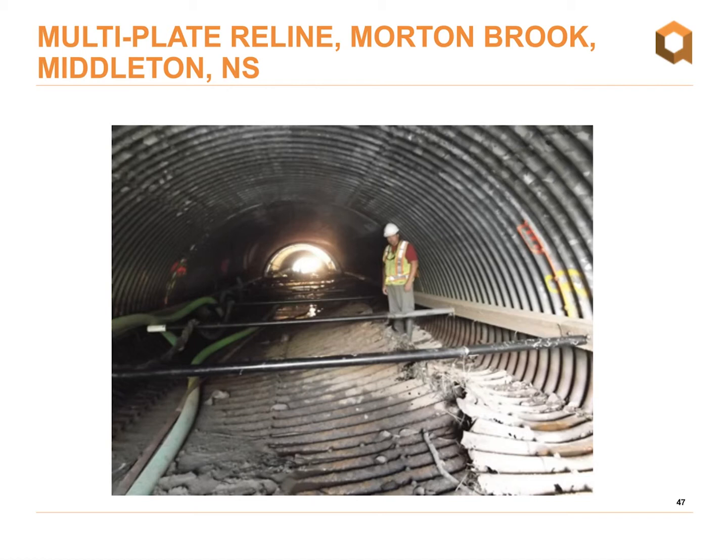So myself and Randy McDonald, who is our engineering director, actually visited this site with TIR to evaluate the structure and provide our recommendation as to whether or not rehabilitation was even an option or if a full replacement was required. So after seeing the site, we suggested that a reline using our tunnel liner plate product would work. This was a very attractive option for the owner as the structure was under 8 meters of cover and a full replacement would be much more costly than the reline option.